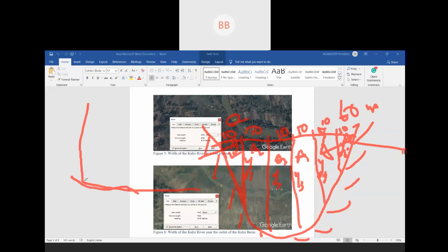We have studied that the velocity at the bottom of the channel is zero, and it increases, and when it reaches the top or surface, it again decreases. So this is the surface of the water. So what people say is, if you take the average of two, that means at 0.2 of y and at 0.8 of y, at two sections, and then you take the average.